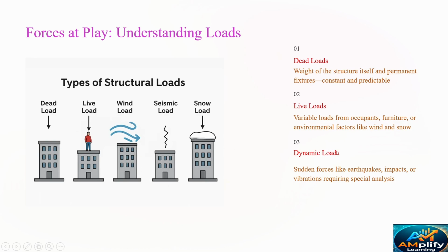What is dynamic? Dynamic means the load changes with time. Dead load does not change with time; it is permanent. Your material's weight is permanent, and your section's weight is permanent. After some days, it will not reduce. But the dynamic load will change with time.